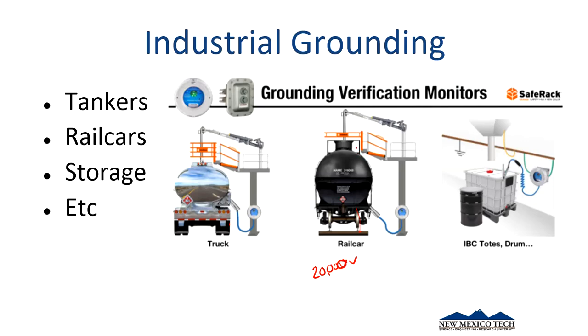The last thing you want to do when you are dealing with a flammable gas or a flammable liquid is have some sort of spark due to this static. So one of the very first things you do is you connect a ground clamp to it to keep it from going off. And same with over here. If you've got lots and lots of fluid flowing through a pump, you can build up a static charge. So you put a ground strap on it. And see, there's our little earth ground over there. These are typically earth grounded, just as a comparison.